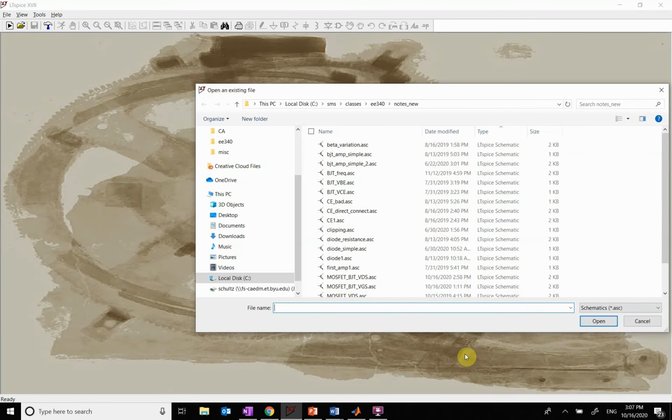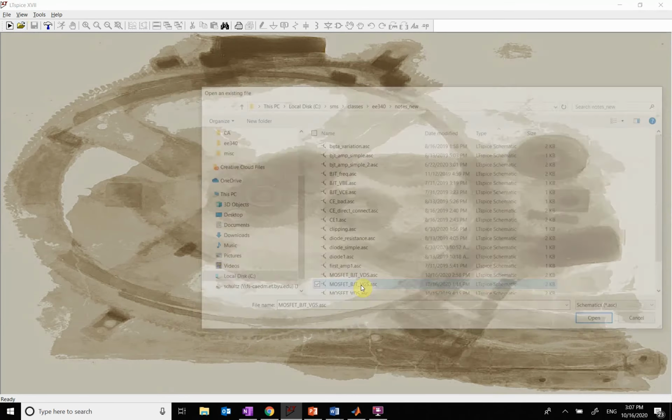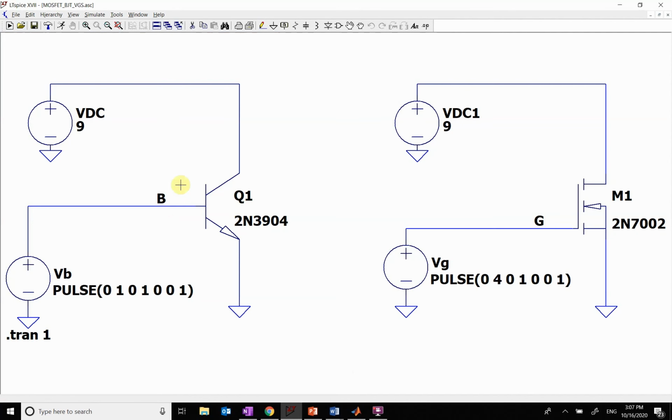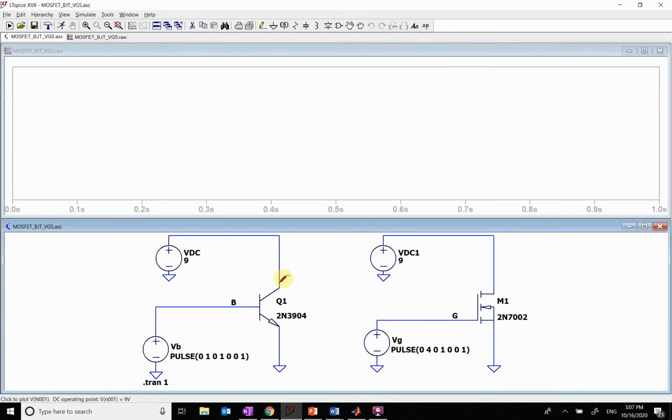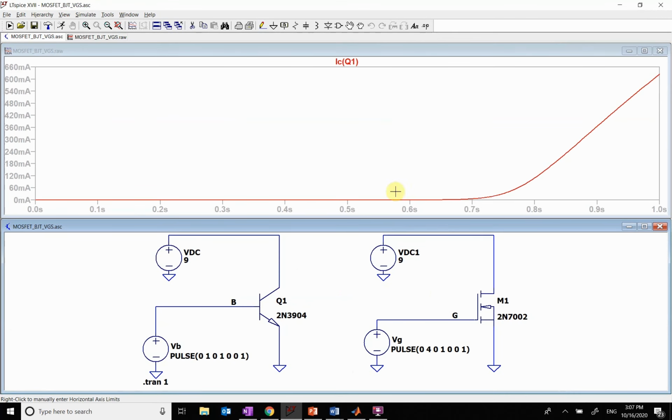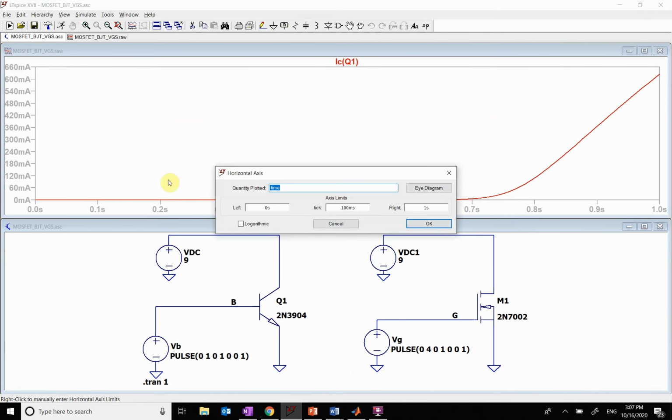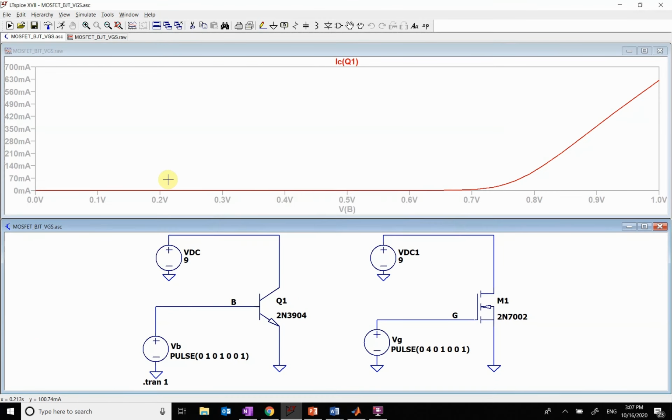So we're going to look at the gate to source first. Here is our BJT that we had before. I'm putting a voltage onto the base emitter, which is my control. If I look right here at the current as a function of V of my base, you see I end up getting this exponential type relationship. I end up getting some RS, and so it ends up going linear when I get to this point. But we see that here's my 0.7 volt turn on voltage.